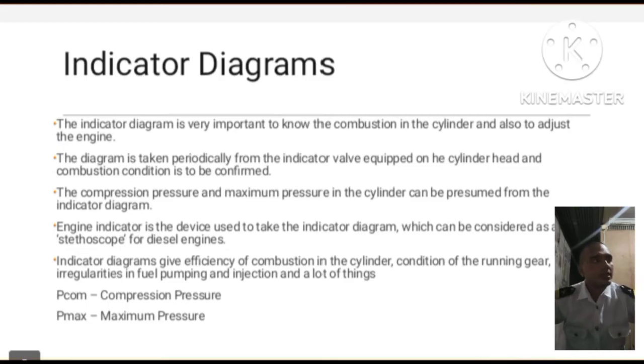Indicator diagrams give efficiency. Why? Because they show the combustion in the cylinder, the condition of the running gear, irregularities in fuel, especially pumping and injection, and a lot of things.